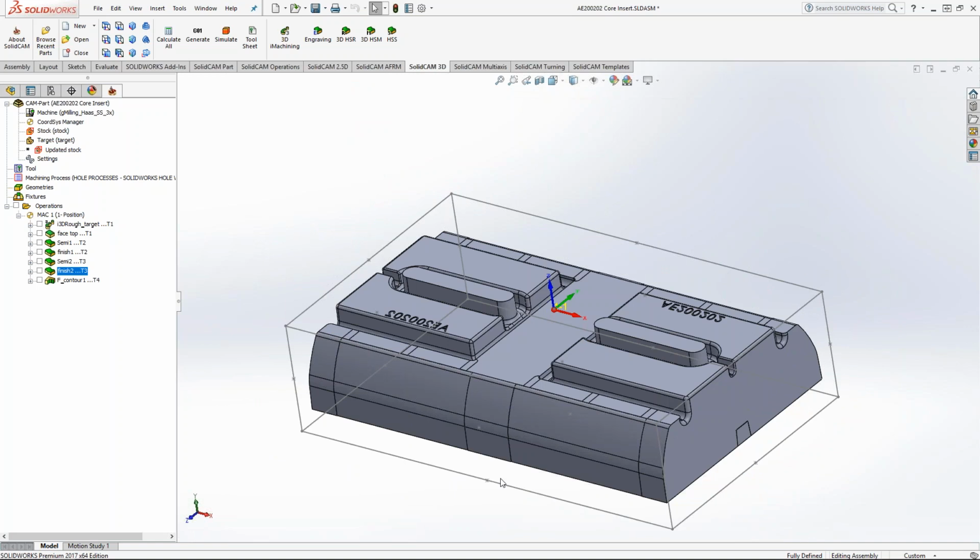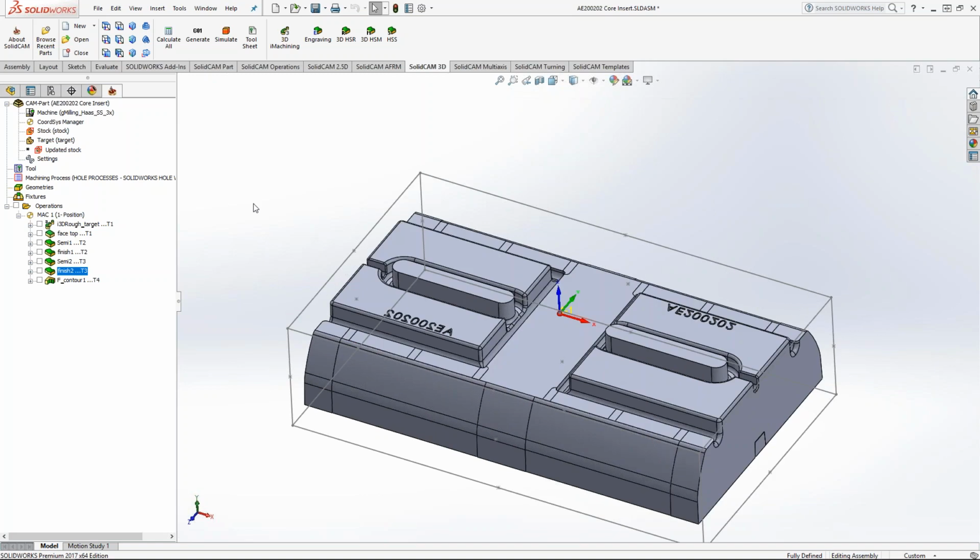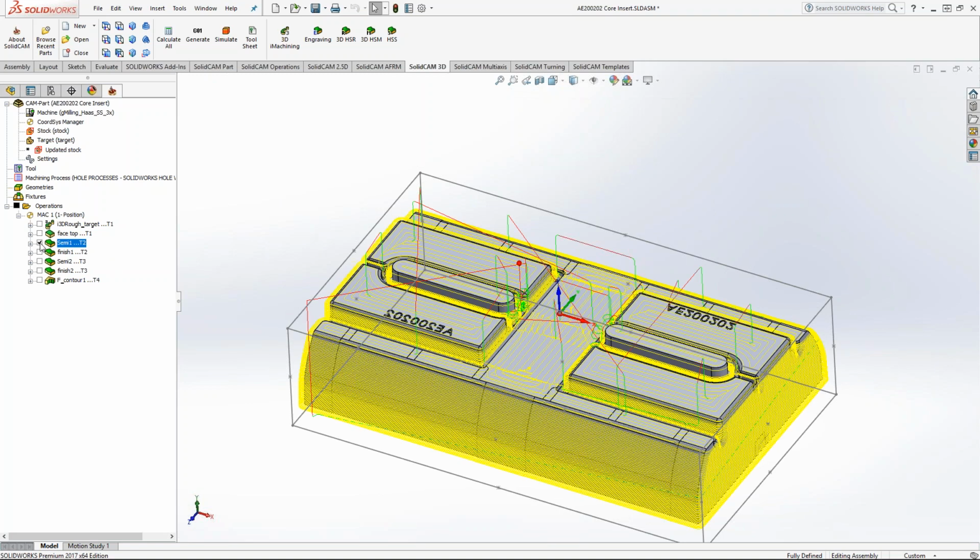Because the 3D iMachining looks at the rest material, I could just step down from a 1/2 inch to a 1/4 to a 1/8 and get pretty close to a near net finish with the 3D iMachining. Now this one I actually did a couple of semi-finish and finishing passes on.